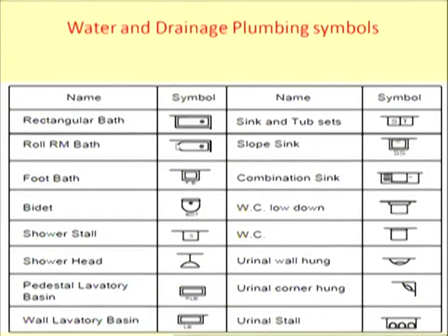So in any building, first we have to create the structure. The structure means it has the structural components like the foundation, substructure, superstructure. Then it will have the doors, windows, lintels, slab. After that we have to put the services. Services means water supply, drainage, and then electrification. So we have to prepare the service maps also.